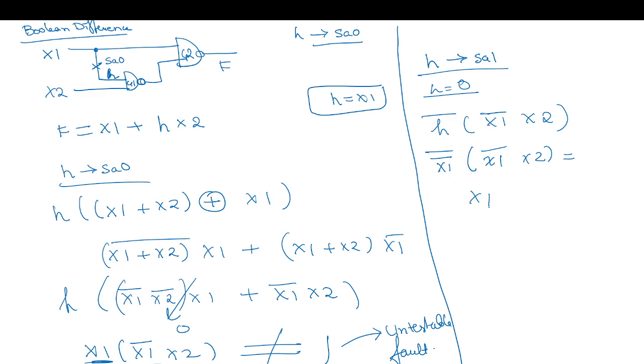So it is x1 complement x2, which is equal to 0, not equal to 1. So this fault also remains an untestable fault.